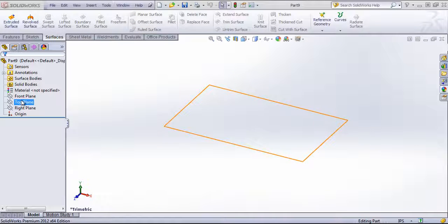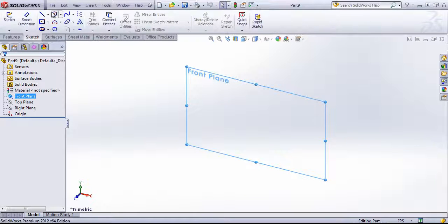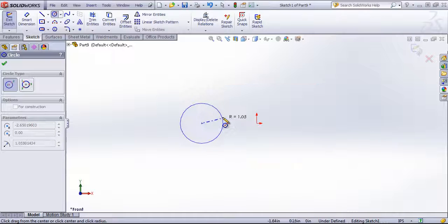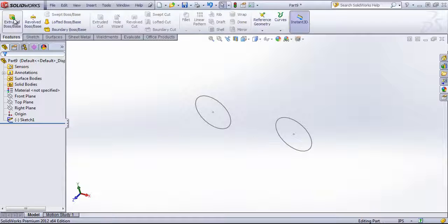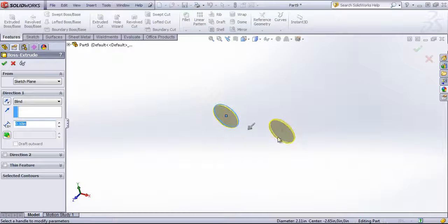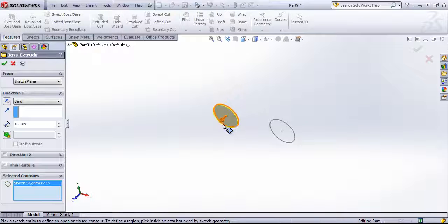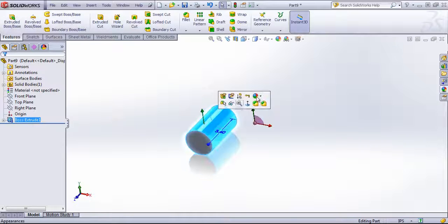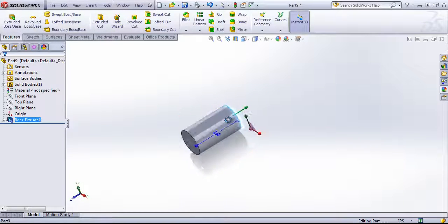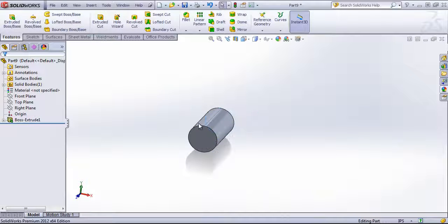One of the important things in approaching surfacing is knowing what's going on in the background in SOLIDWORKS. Any model you work with is pretty much just a simple series of surfaces that are enclosed in a volume. So if I create an extrusion out of a circle, for example, what I really have here is three surfaces that are all just merged together and form our solid body.